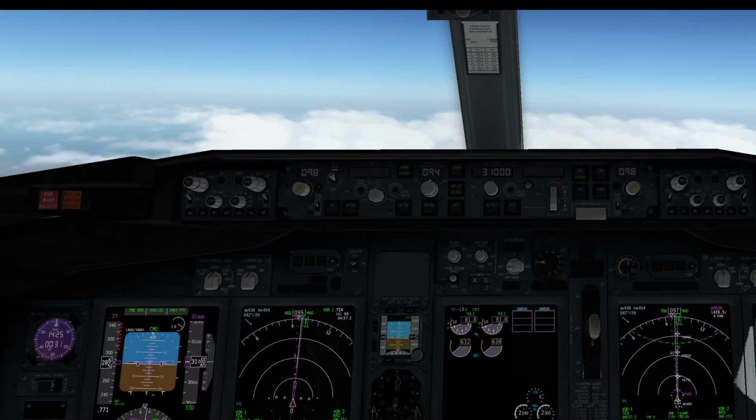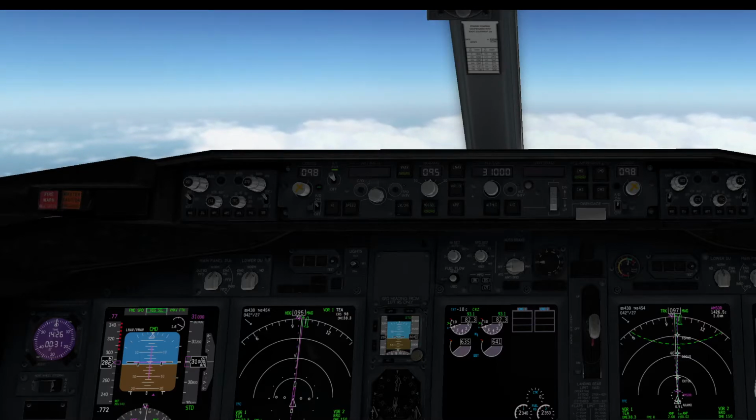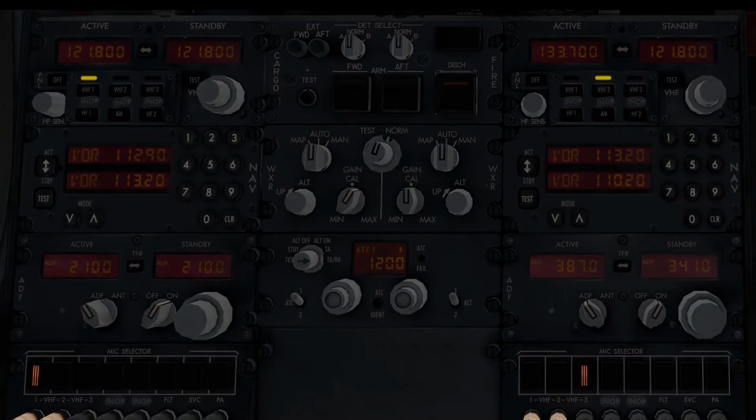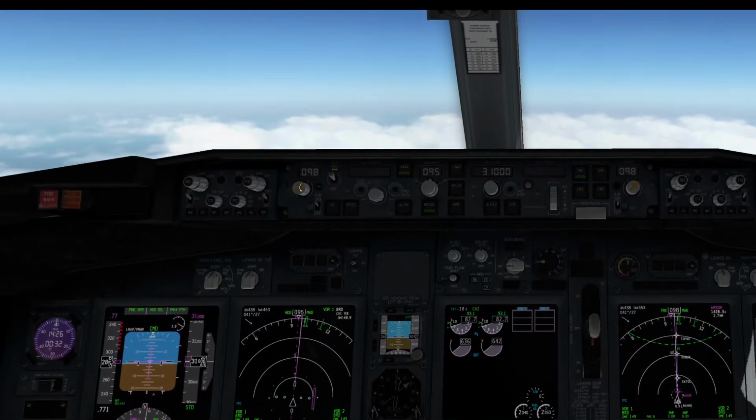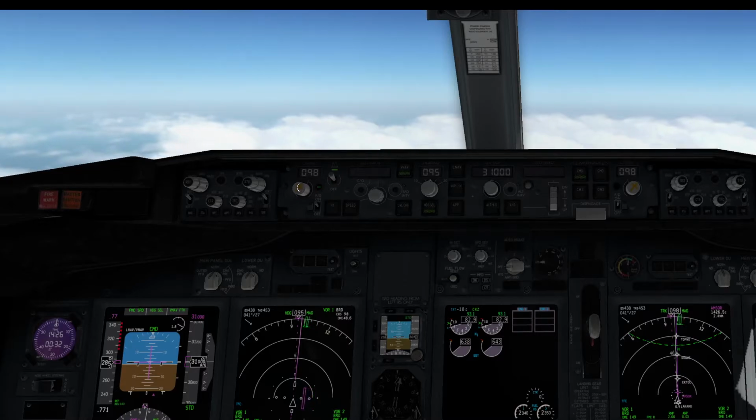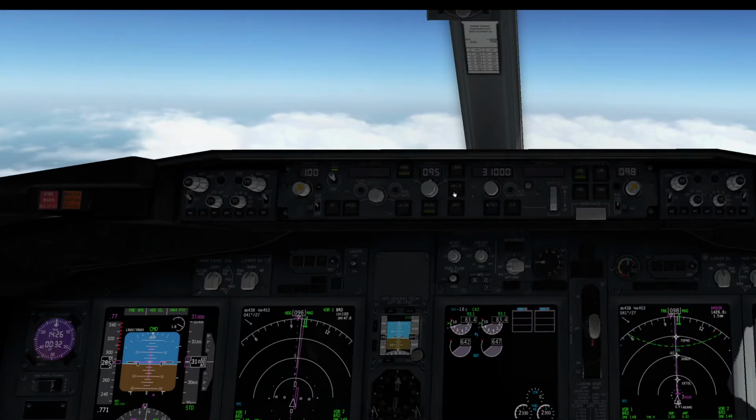In the meantime, we have the Brindisi VOR tuned, so let's go to heading select, switch to the Brindisi VOR 113.2. No change in the course, and select, well, we could use 100, why not?